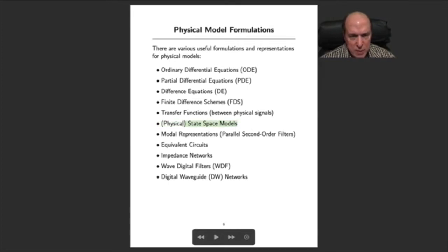Now, if you take a state space model, it tends to be a little expensive. It can be, although Jan Orlari did some interesting benchmarks that showed that for the cases we tried, such as a biquad filter, the state space model was about the same as just a normal direct biquad implementation using direct form 2, the standard things that are in the libraries. That's because these are sparse matrices and the compiler is good at optimizing and not computing anything unnecessary, so that you can hope that your state space model will run at the same speed as your ordinary transfer function